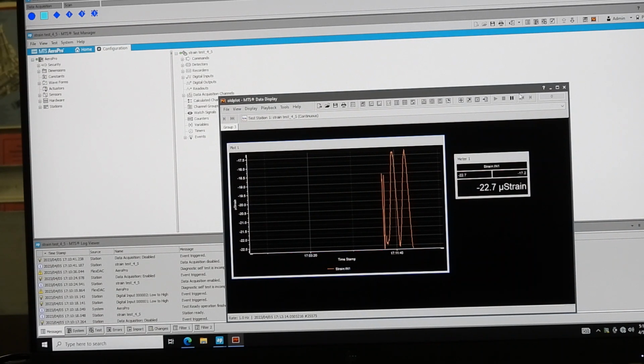Because if we don't know what it's going to trigger... Well, you don't know when it's going to trigger. You don't know what the voltage is when it's disconnected from anything, sitting in open space. But even when it's connected, it can fluctuate and pick up some noise of a couple of millivolts. Sure, the trigger level here is above 3.5 it turns on, below 1.5 it shuts off. So you've got a 2-volt window there. If you have that much fluctuation in your cabling, you've got problems.